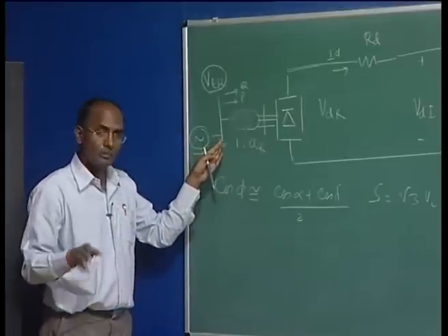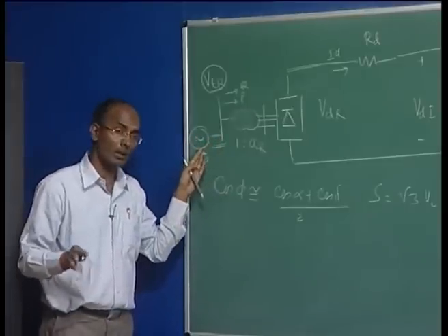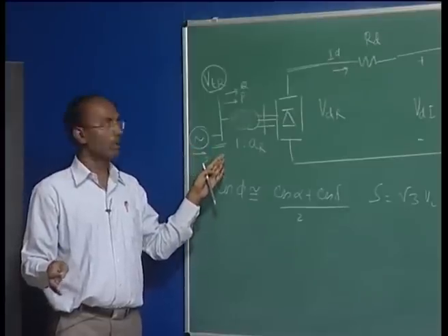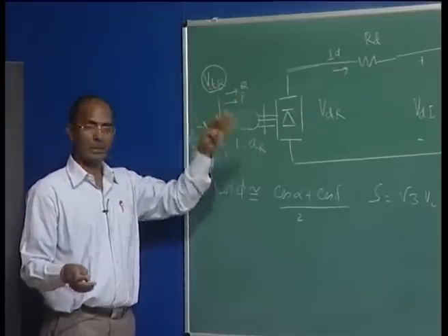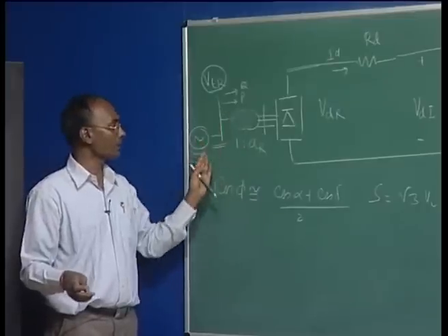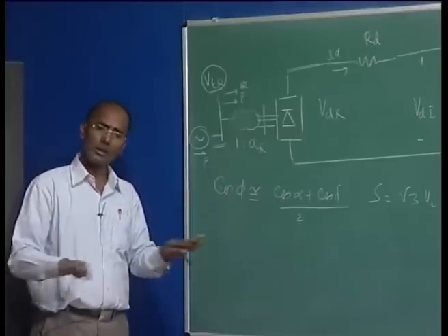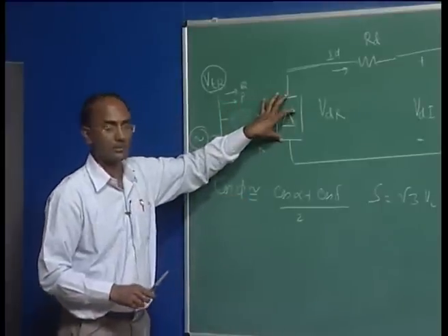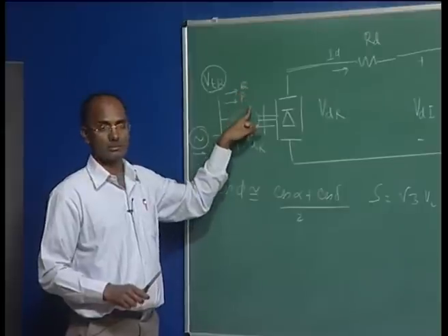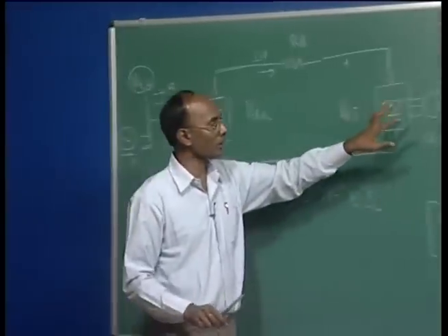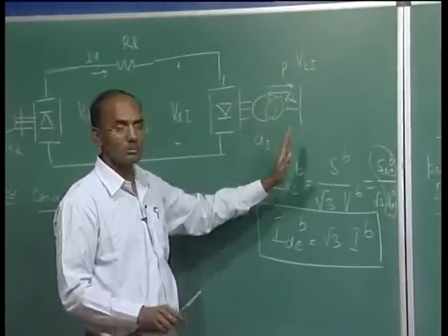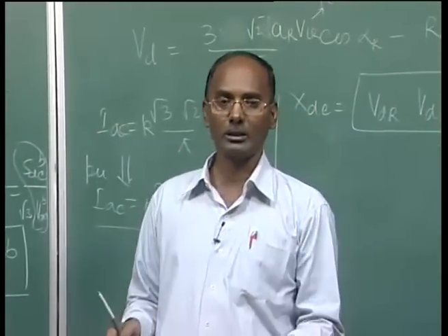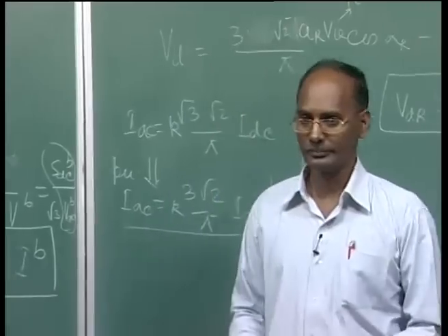Whether you are taking it as a load bus or generator bus depends upon whether you are having a generator or not. If you are having a generator, you can take it as a generator bus, this will be the negative load at this, and then you can solve it. And you have to check its reactive power generation, what is the reactive power taken, and this is similar to AC load flow, no change at all. Only here you have to take this DC system equivalent to the PQ load, nothing else. Here also you have to take this P as negative and this is Q of the DC. You can say the DC system is just represented as equivalent real and reactive power loads, nothing else.